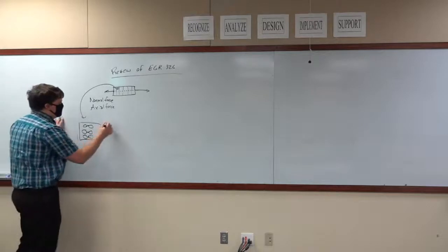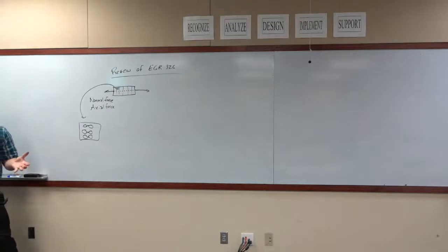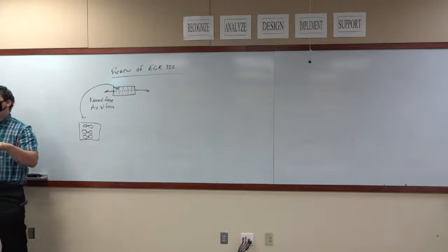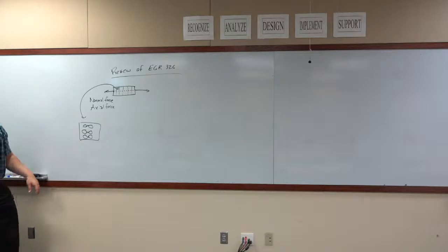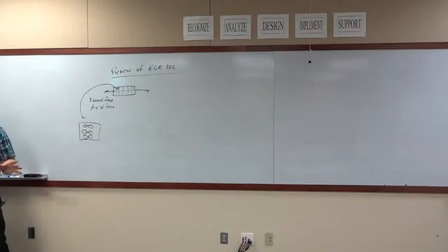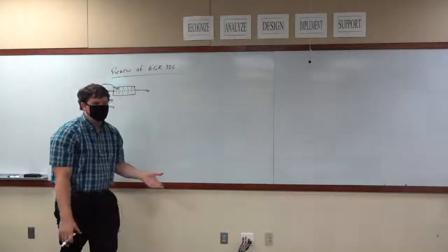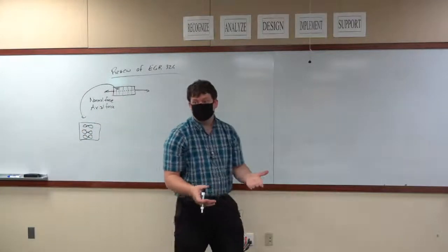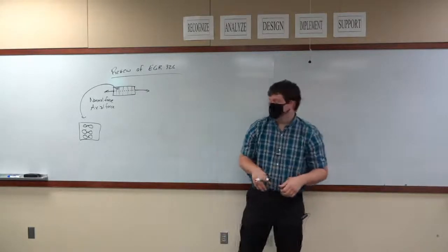Now, what you end up having in this type of situation is, if you look at the material really closely, the atoms all bond into very nice, neat structures called grains. The grains have boundaries between each other. But there are actually going to be holes in between the atoms and the molecules in this structure. They're small enough that you can't see them. You could use an electron microscope and you could scan a surface and you could find one, as much fun as that is. But they're everywhere inside of this material.